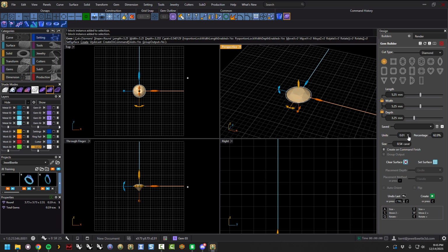Now, if we are in hundredths and you want a 5mm, but you don't want to go change it or type it, you can hold down Shift, okay, and we will snap to 20ths. So you can get to 3.4 and you're good to go, okay?